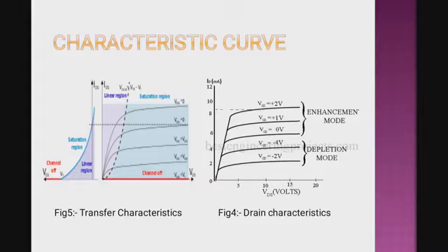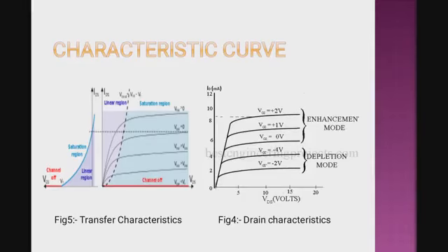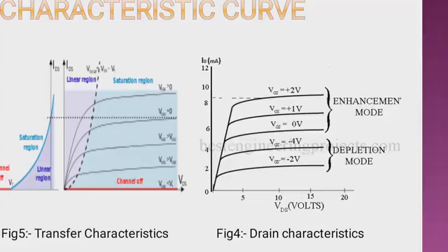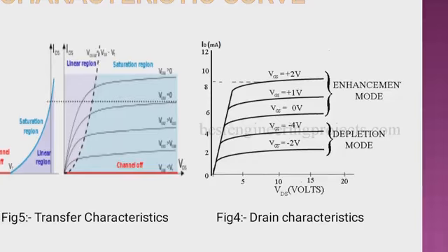The drain current becomes constant at a particular voltage, and this particular voltage for this plot, when Vg is equal to minus 2 volt, is called the pinch off point or the pinch off voltage, because here the current becomes saturated but the voltage is increasing along the x-axis.